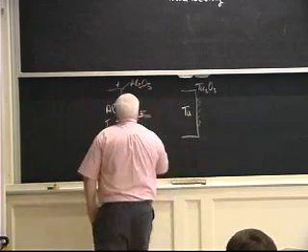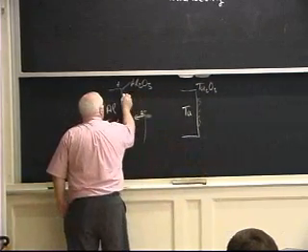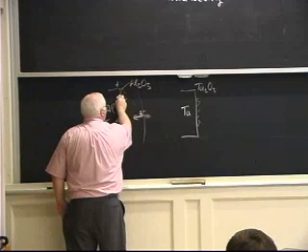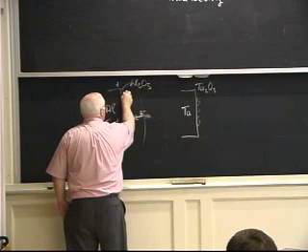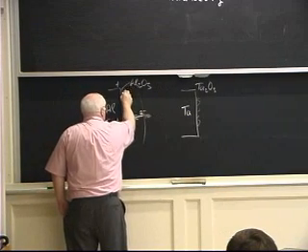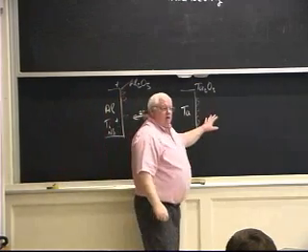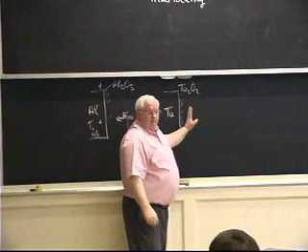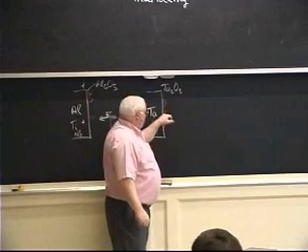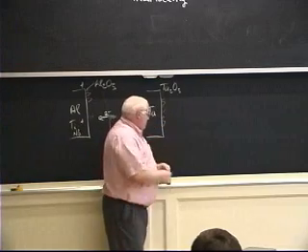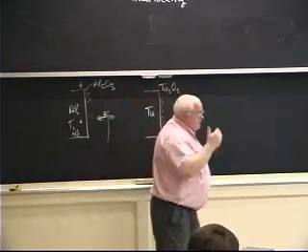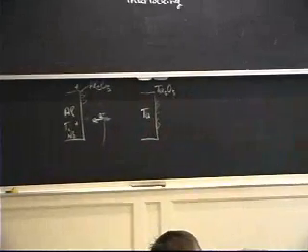And you have to have spaces in between in the electrolyte where the oxide can go, or the electrons can go. Otherwise, this aluminum or this tantalum oxide are very, very good insulators. If they were continuous across here, then you wouldn't be able to pass the electrons in the anodizing process.